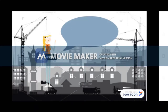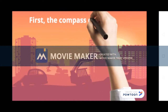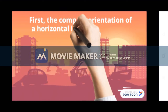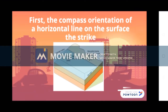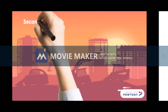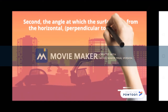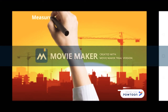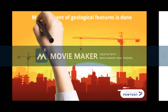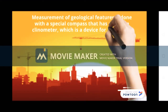We can express the orientation of a bed or any other planar feature with two values. First, the compass orientation of a horizontal line on the surface, the strike. Second, the angle at which the surface dips from the horizontal, perpendicular to the strike, the dip. Measurement of geological features is done with a special compass that has a built-in clinometer, which is a device for measuring vertical angles.